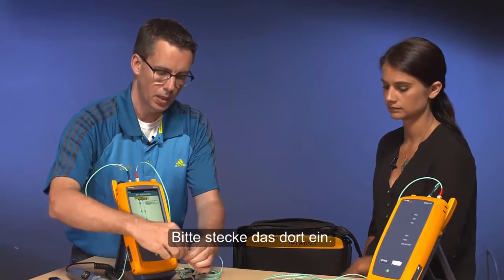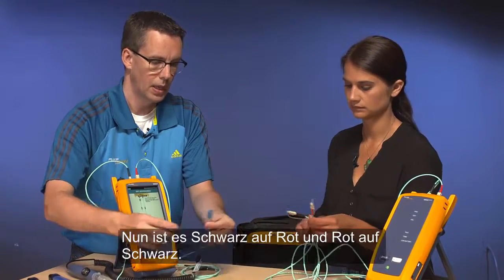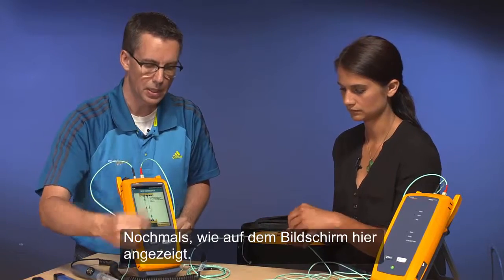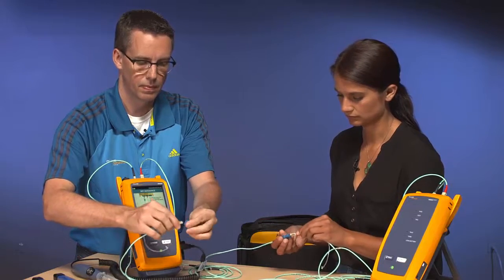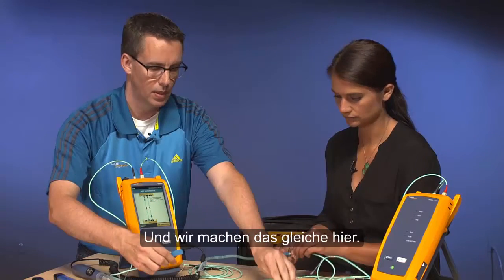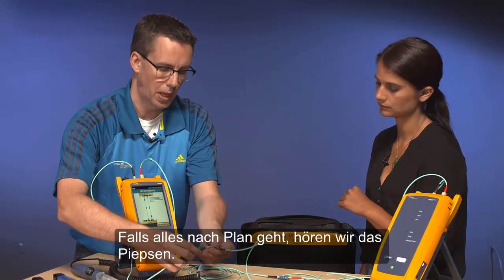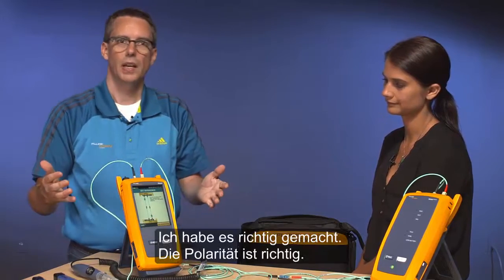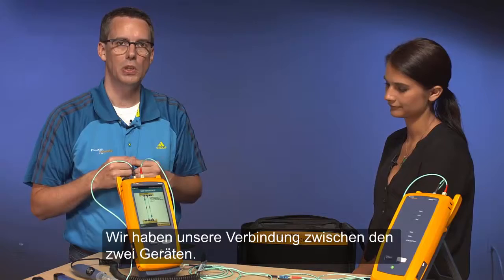So I'm going to plug this one into here. And it's black to red, red to black. Again, that's indicated on the screen here. And we'll do the same here. And if all goes to plan, we'll hear a bleep. I got it right, got the polarity correct. We got our continuity between the two instruments.